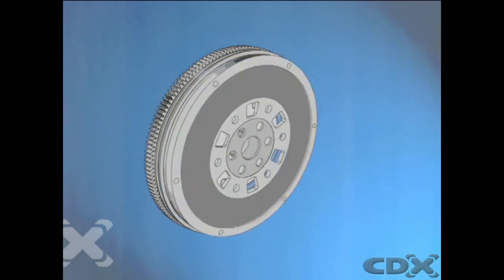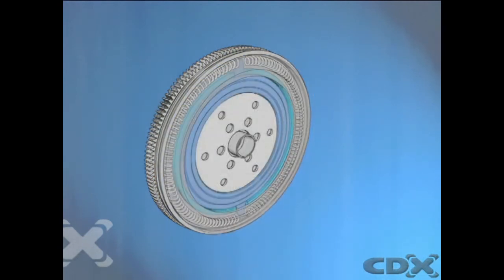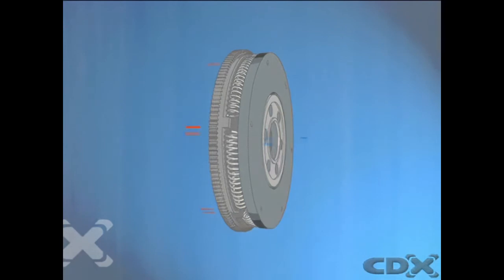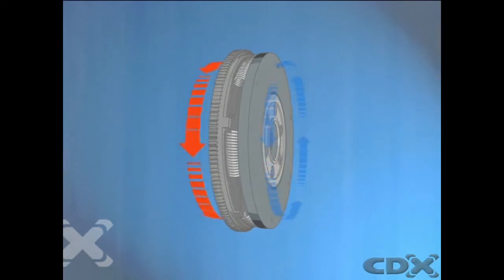There is a friction ring located between the inner and outer flywheel that allows the inner and outer flywheel to slip. This feature is designed to alleviate any damage to the transmission when torque loads exceed the vehicle rating of the transmission. The friction ring is the weak spot in the system and can wear out if excessive engine torque loads are applied through it.